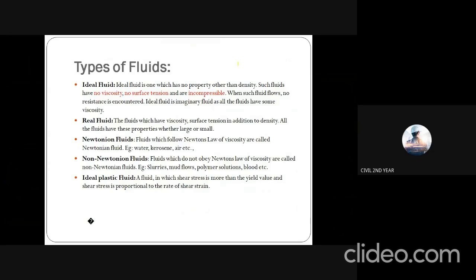Whereas non-Newtonian fluids do not obey Newton's law of viscosity. Examples are slurries, mud flows, polymer solutions, blood, etc. An ideal plastic fluid is a fluid in which the shear stress is more than the yield value, and the shear stress is proportional to the rate of shear strain.